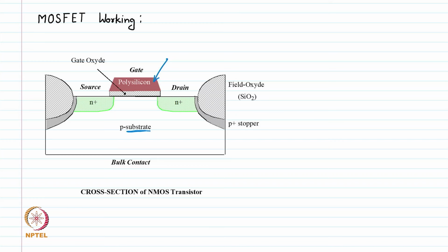It means this region is rich in positive charges, or we call the holes. So this positive charge is everywhere in this p substrate, and on top of this we have source region where this is doped N plus. It means there are electrons everywhere. This region is rich in electrons, which is negatively charged. So if we see closely, this negative charge is here, negative charge is on the drain side and source side.